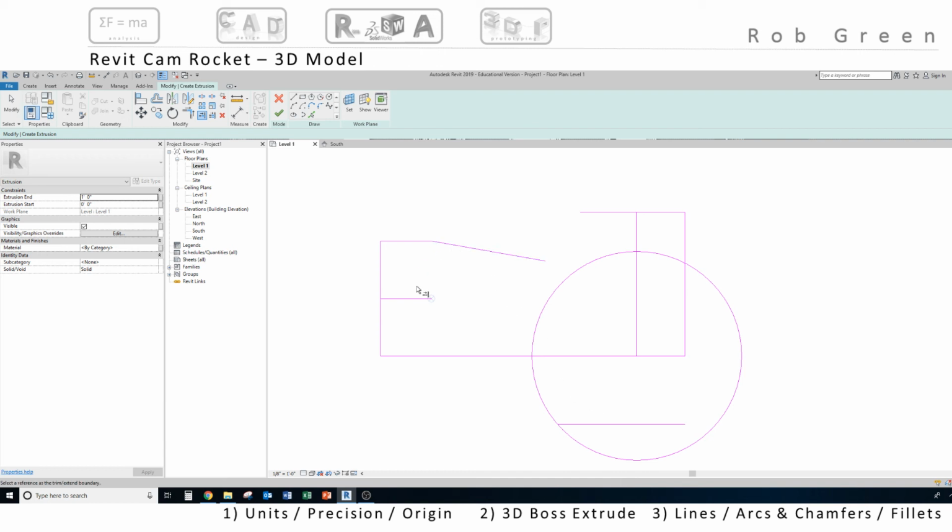So I'm going to extend this first horizontal line all the way over to the right. And notice that I'm still in my extend command. You can look at the cursor and see that the extend command is represented with a little figure right by my cursor. So I click this vertical line and I want to extend my horizontal line, and I click that, and I'm then ready to draw this line that comes all the way down at an angle.